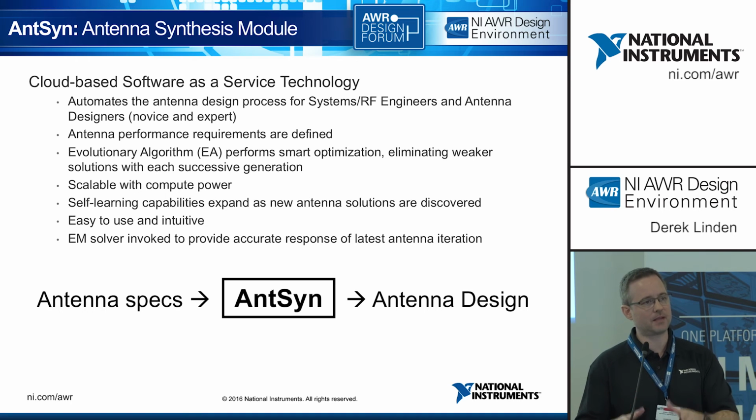In this software, you define your performance requirements. You don't enter a model directly. You enter what you want the antenna to do in terms of frequencies and pattern and gain, etc. And then we have an evolutionary algorithm that performs optimization and that continually generates better and better models based on your specifications.